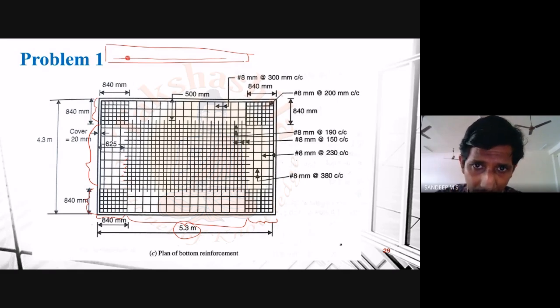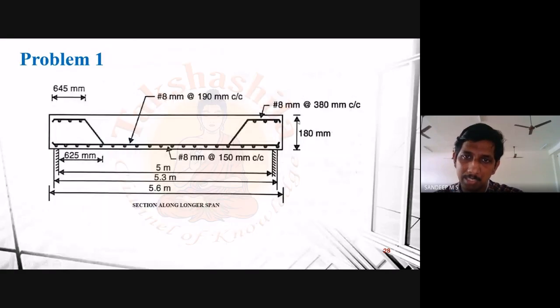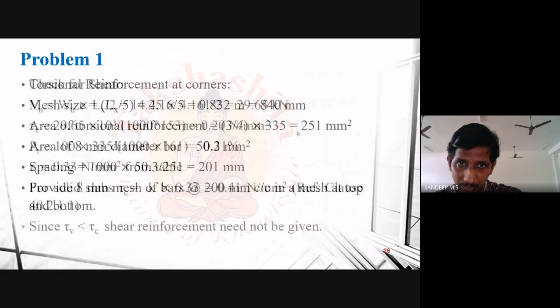now. Okay, and again if you refer somewhere here to this reinforcement, this one and this one are actually shown by this arrow, and it is 8 millimeter at 190 center to center spacing. That is the reinforcement we have already designed with respect to Ly direction.